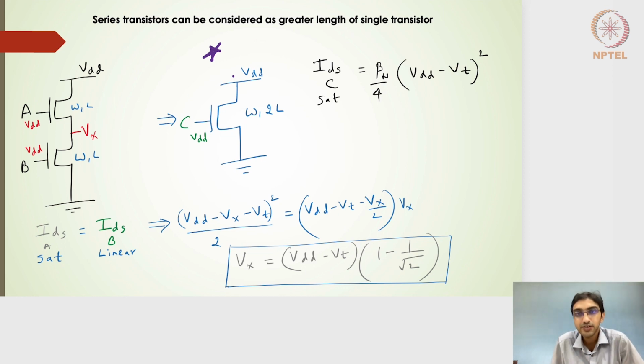What I mean by standalone is it is not connected to any PMOS transistors or any other part of the circuit. So it is a single NMOS transistor where one side is connected to the VDD and another side is connected to the ground. What it implies is the side connected to the VDD should be the drain terminal. The other one, connected to the ground, should be the source terminal. And this is the input, supplied with the VDD value.